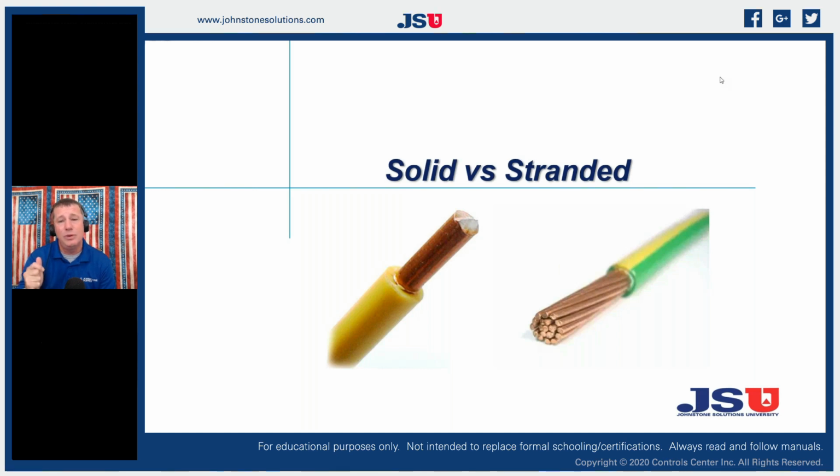Because in the past, we've used our thermostat wires as a path for current. We were actually using 24 volts AC, and we were applying a load across those thermostat wires. So we were using those as regular conductors, right? We were passing current through the conductor so that we can operate a load on the other side. So we had voltage and we had load, so we had potential running through those wires. And we were doing a fair amount of work with those.